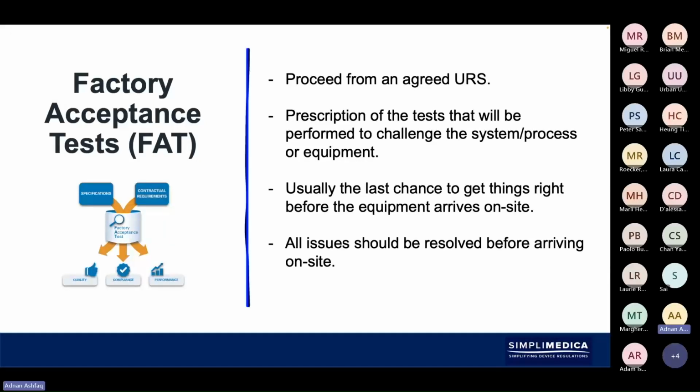Before we actually get into the heart of the qualification, before we get anywhere near installation qualification, we're looking at ensuring that the equipment is going to arrive as we requested, and we've done some level of testing at the supplier site. It can even be things like dimensional checks to make sure that it's going to arrive in a crate at your site protected, and it's going to be shipped with adequate packaging and protection before it arrives at your site.